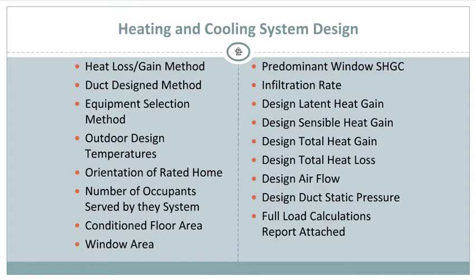We'll be talking about window areas. You're going to want to measure every window. The way you measure those windows, it's going to be from the top to the bottom, left to right, width. Again, remember when you're measuring windows, you want to make sure that the windows meet egress. Egress is considered, you've got to have at least 24 inches minimum opening height and 20 inches wide, for that window to meet egress. So in order for somebody to be able to crawl out of that window, and they can't be disturbed with anything else.